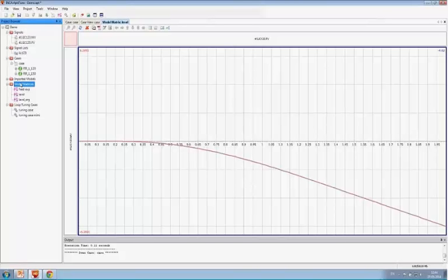Another thing is nonlinearity. So how can you deal with nonlinearities? Valves seem to be a very good example, with CV curves of valves which are far from linear. If you step through a big range of the valve, you can see nonlinear effects, and you can account for that in several ways.